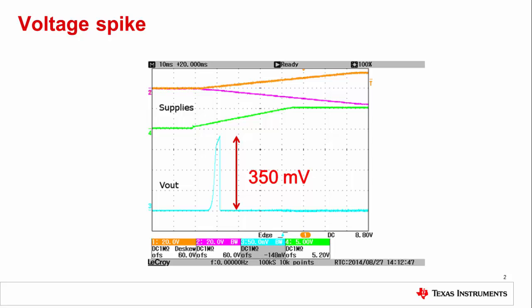Imagine that you are working in a motor drive application, and as you power on the system, the motor moves a little. In this and many other applications, this kind of behavior is unacceptable. What caused this sudden movement? It might be the DAC creating a large power on glitch.